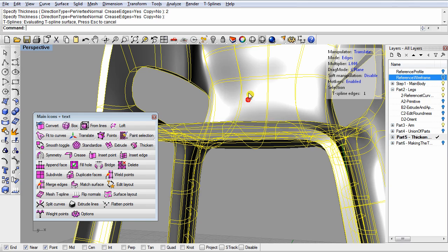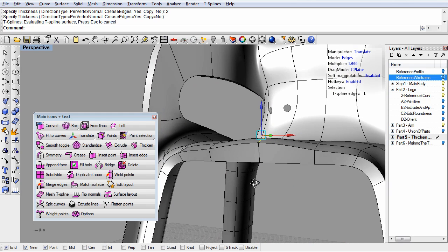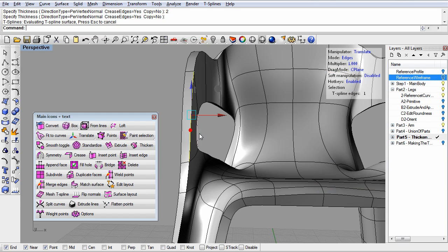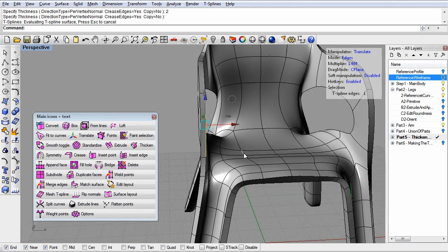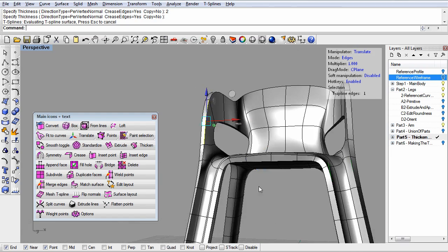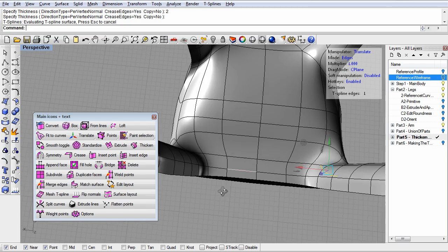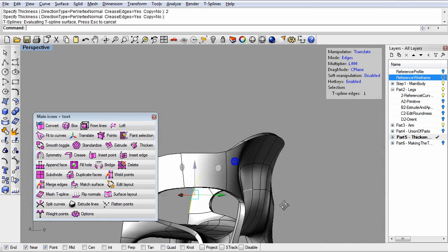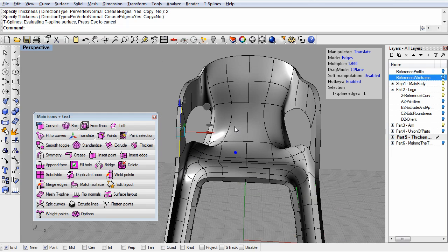So I can still, if I want to get a variable radius here, or a variable thickness, just move the different parts of the T-spline. This thicken command does not give you a constant thickness, nor does it guarantee that the model won't self-intersect. So depending on how big it is, we can probably look around and see if there's self-intersections. I don't actually see any self-intersections on this one. But if we throw a clipping plane on this, let's see.